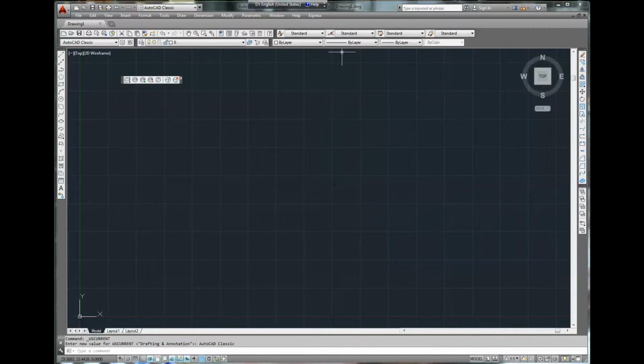And we get more pop-ups. We'll get rid of those. Now the next thing we're going to do, down here in the command line, we're going to type startup. Some of the older versions don't have this screen up here. Everything gets typed in down below, but it doesn't matter. If you type it, it goes into the system. And here you see down at the bottom, it's asking for a value, and we're going to give it a value of 1. If you've got the older versions, your 1 will appear here. This has got a system where it shows up in a different window.